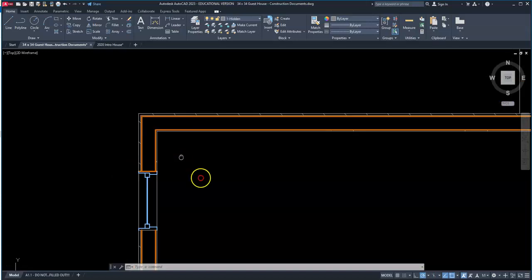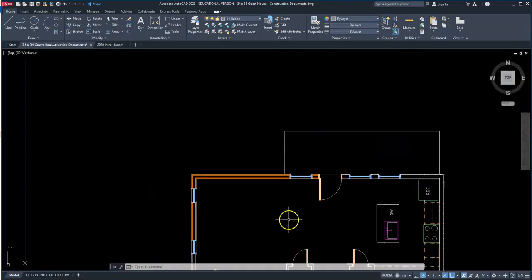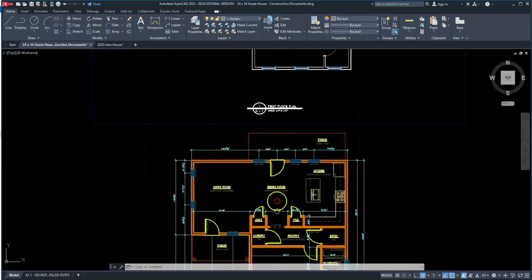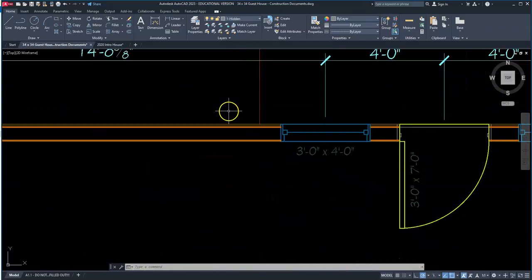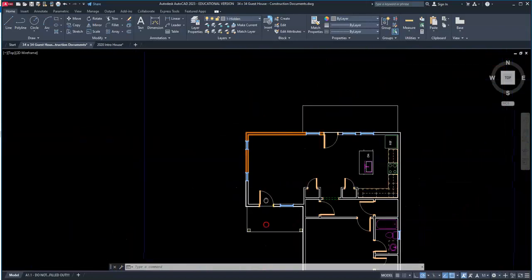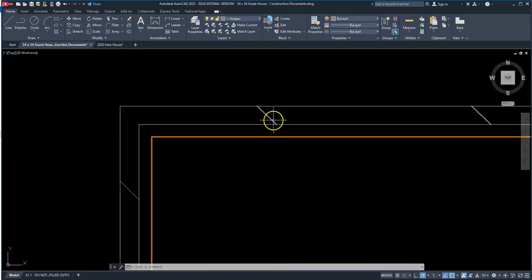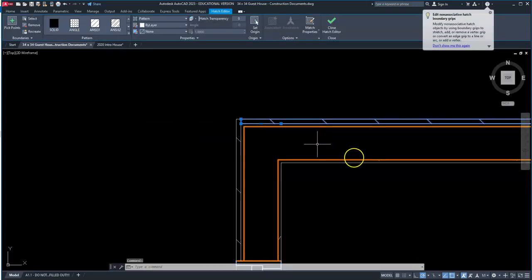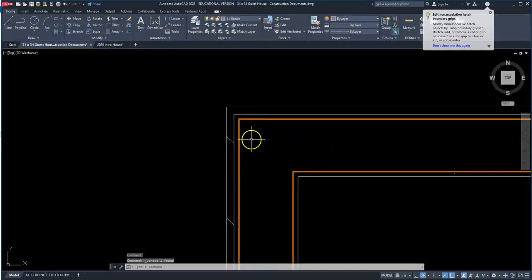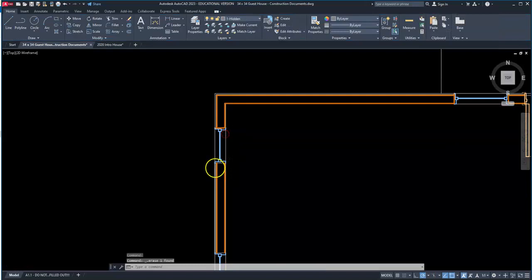Alright, so now that you've created all of your wall stud lines in the correct layer and have what we see here on the bottom, just for wall studs, we will go ahead and change our exterior and interior sheathing lines. Revit will give you a little bit of a hatch pattern inside here. We're going to delete that. That's not necessary.